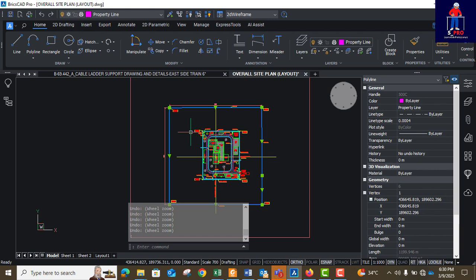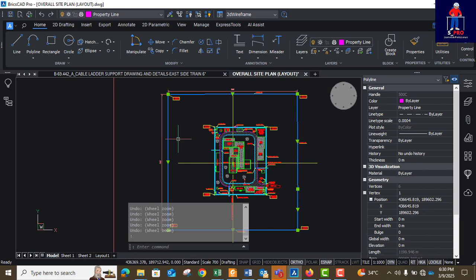That's the whole property, but that's the boundary. Now in oil and gas, we don't start building from the property line. You have to give a distance away from the property line to put your fence, and normally the standard is 1 meter. So if this is a gas processing plant where we need to make use of the whole purchased area, we can just offset 1 meter.